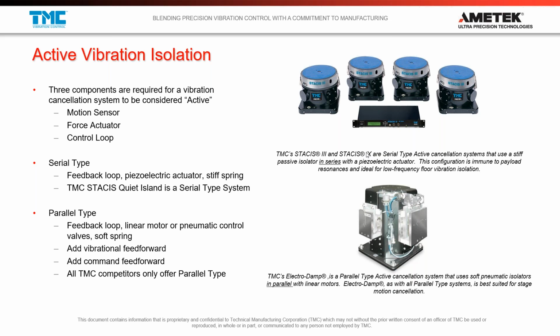Like a self-leveling system isn't necessarily an active system. It's a closed loop control system, but it's not necessarily an active system. It's not really actively actuating against the sensor. It's really just sensing with the leveling arm the position of the table, and then that leveling arm will either open or close an air valve. So there's really no control actively. It's a motion sensor controlling a valve. So be careful, because a lot of folks will call an actively leveled top something that is actually not an actively controlled top.